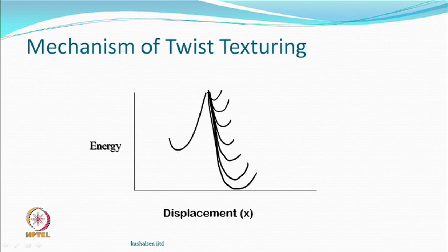Now, this is the energy curve that you saw before. This is state x1, where the multifilament yarn as it is was stable. There was no changing its configuration, it was stable. And what do we do? We have done twisting. When you do twisting, the energy goes high. Okay. The energy goes high, increases. Why? This is the strain energy, deformation energy.